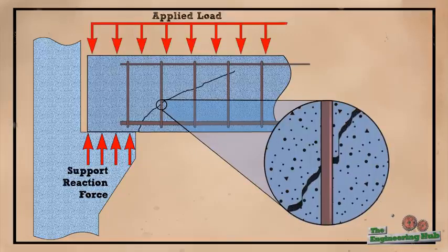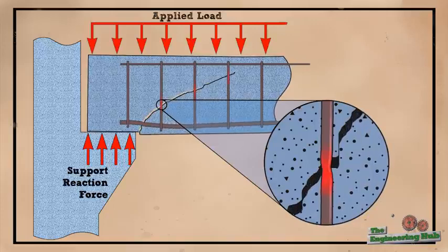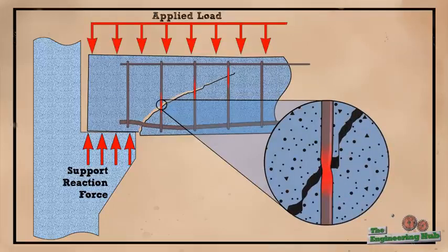This is the critical point where the stirrups get activated and prevent full separation and sliding of the concrete. The stirrups prevent the sliding motion and begin to carry the shear force that used to be carried by interlocking. Interlocking tends to lose its resistance due to the widening of the crack, and therefore it is unreliable and is ignored in the calculation of the shear capacity of the beam.